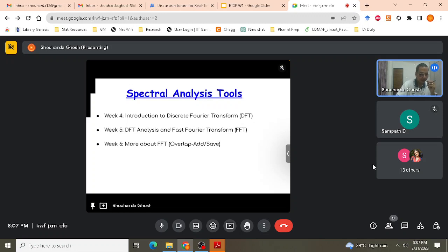But we cannot implement all these things on the platform. Continuous time Fourier transform, you can understand, works with analog signals. And even if you try to work with analog signals, the frequency range is continuous. Now your computer has finite memory, you won't be able to store infinite numbers on your computer, right? So your computer is a finite state machine. You have to do all the processing in your finite memory. Even your analog signal has infinite precision. You take a voltmeter or you get some kind of reading from a sensor, that's infinite precision. But in reality we have to quantize these signals because of the finite space of a computer. So we use finite length transforms.